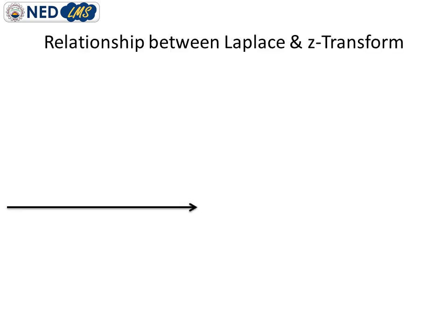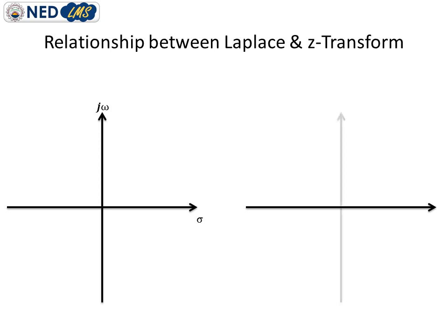If I want to express the S plane and Z plane graphically, then for S plane you already know sigma and j omega are orthogonal to each other, and this constitutes an S plane which belongs to the Laplace transform. And for Z plane we came to know that we have a complex frequency represented in the polar form. So in the polar form, the x-axis is basically representing the real part and the y-axis is basically representing the imaginary part.